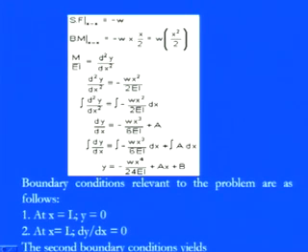So with that, the shear force is equal to minus W, and the bending moment is equal to minus W into x, that is the load, into x by 2, which is the pointing there. So we have minus W into x square by 2. By keeping those values in the basic equation of the deflection, that is M by EI equals d2y by dx square, we have d2y by dx square equals minus the bending moment, Wx square by 2, so minus Wx square by 2 into EI.